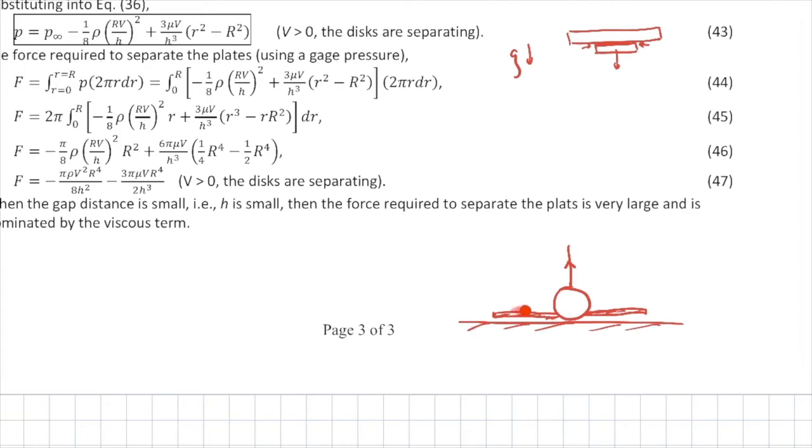The wings adjacent to the bottom surface of the ocean just looked like these parallel plates. And when they were trying to lift it up, this produced a lubrication layer where the fluid had to rush in underneath the wings into this region, and they got a very low pressure region down here, and so it was a very large force, particularly when this gap height was small.